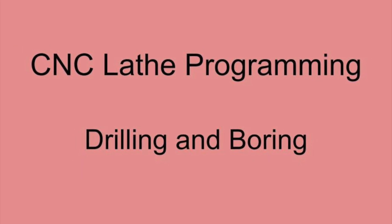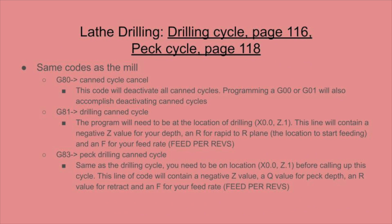Hey everyone, this video is going to be on CNC lathe programming of drilling and boring using the TL lathes in our shop. You can find drilling information between pages 116 and 118. They're the same codes as the mill, with G80 being canned cycle cancel, G81 being a drilling canned cycle, and G83 a peck drilling canned cycle.